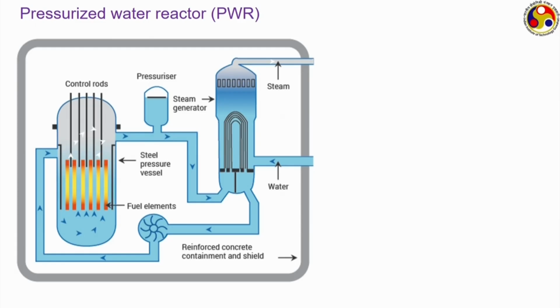So, when it comes out of this fuel bundle, this same water is at a reasonably high energy level, and if we can maintain the water under liquid condition, then definitely its temperature will be much higher than the inlet temperature. The water comes out of the reactor here, and between this point which we can mark as 1, the inlet for this water, and this 2, the outlet of the water, there will be a significant difference in the energy level or enthalpy of this water, but physically both of them will remain liquid.